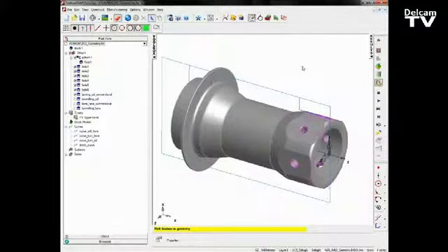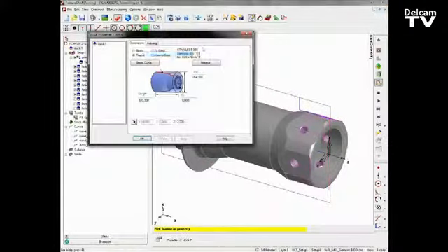So the first area we can see here, we've got a series of flat faces and holes, so we're going to have some interrupted cutting as it tries to turn the majority of the material. As well as that, the material we're trying to cut in this particular instance, if I go to the stock and look at the properties, you can see we're using a 302 stainless steel.